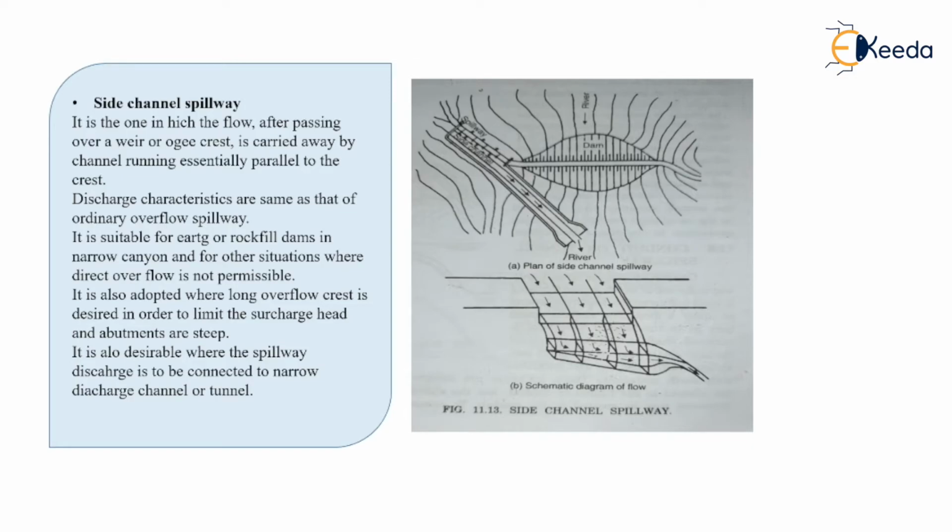For this criteria only, we are locating the spillway on the bank sides of the dam structure. This type of spillway is also suitable for an earthen or rock-filled dam. It is also adopted where a long overflow crest is desired in order to limit the surcharge head and abutments are steep. It is also desirable where the spillway discharge is to be connected to a narrow discharge channel or